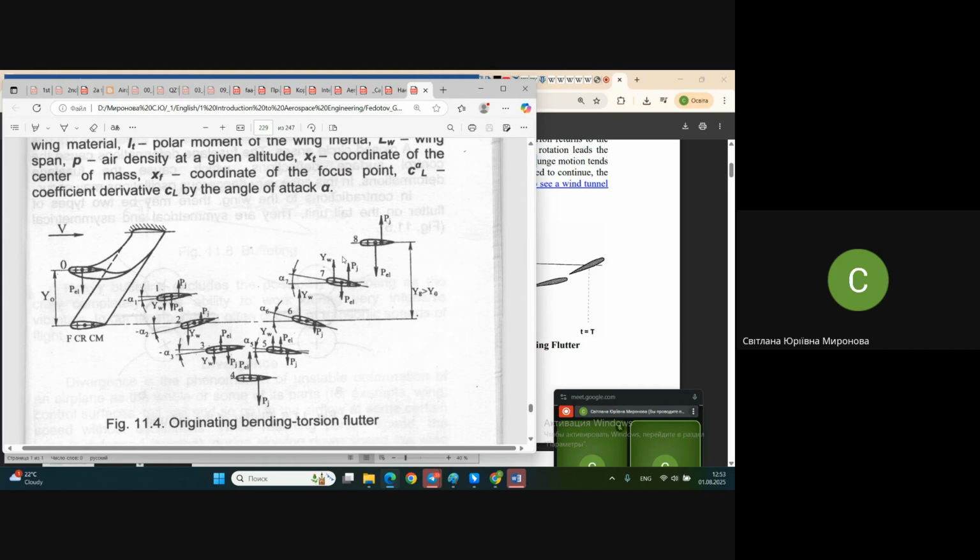Now, what is the problem in this case? The problem is that some surfaces become unusable, uncontrollable. It's not just the question of dreadful vibrations in the airplane or in some places of the airplane. Control surfaces are not going to work in this situation because the downwash is abnormal, and the effectiveness of control surfaces, you do remember, depends on the area of the control surface that has to create additional forces that we are going to use for control.